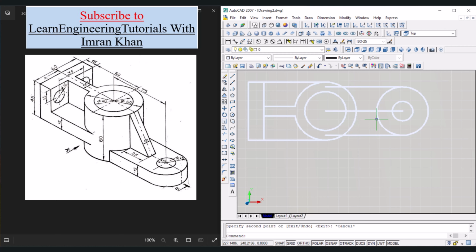Again use trim command, so tr, enter. Click over here and over here as well. Press escape. Click on this line and press delete. Now write tr, enter, and bring the cursor over to this area, and because this is a separate line segment, we have to remove this. We cannot trim this object, so press escape, click on this object and press delete. Now the top view is almost complete except this triangle.